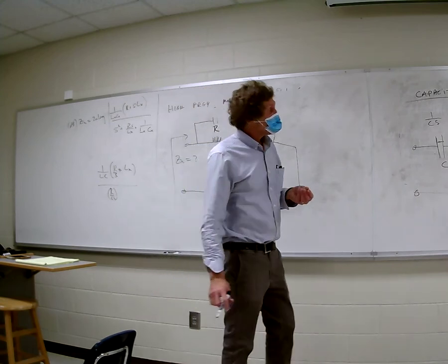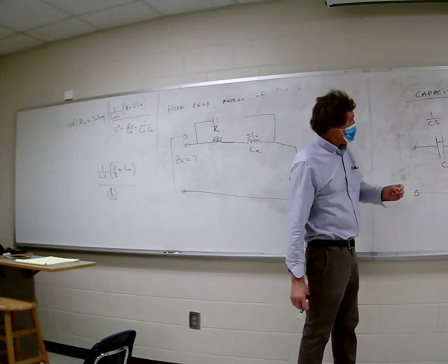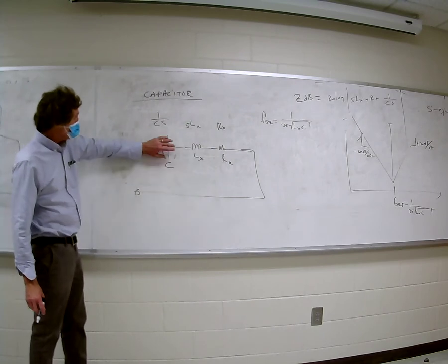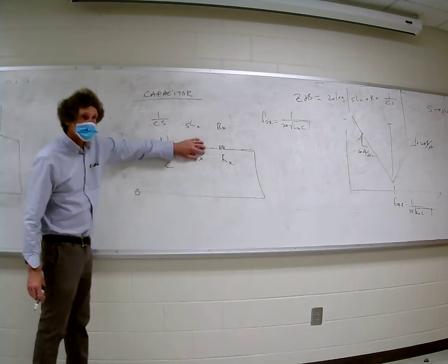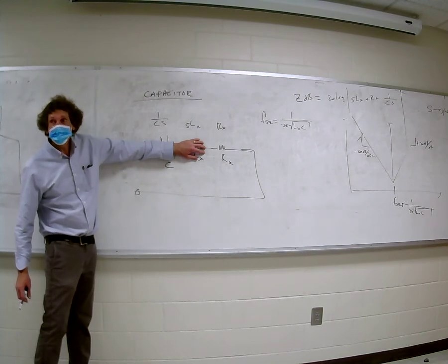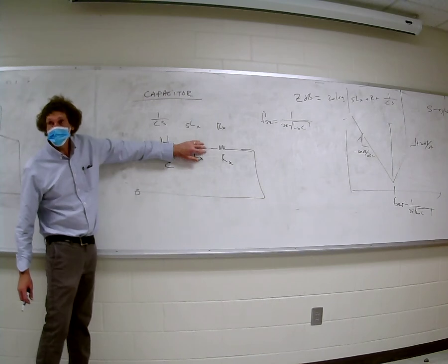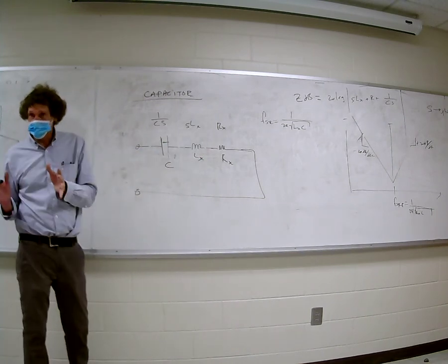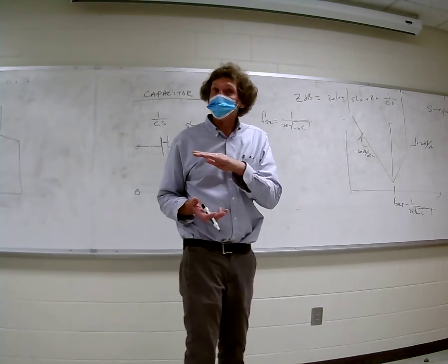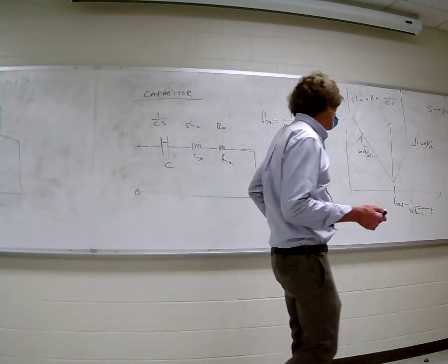What it really means is the reactances cancel. If I take a look at the self-resonance of this thing, it means the reactance of this and this cancel. I just have resistance. Are you with me, class? Remember that always. When we talk about resonant frequency, inductive and capacitive reactances cancel in terms, they're the same magnitude, opposite signs. If they're in series, that's the case, and if they're in parallel, they look like an infinite value.